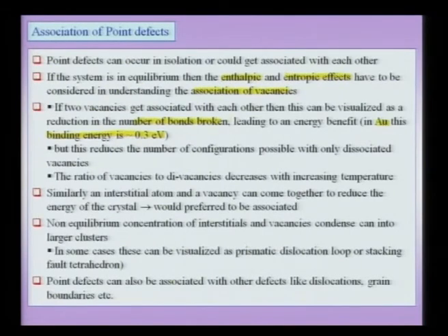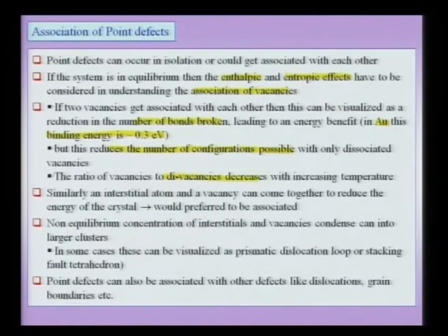And as I also pointed out, once I have this divacancy formation, it reduces the configurational entropy of the system. So, as a function of temperature, there would be not only an equilibrium concentration of vacancies, but also an equilibrium concentration of divacancies, and I would expect that with increasing temperature the divacancy concentration would increase.